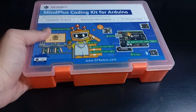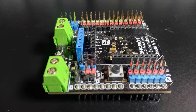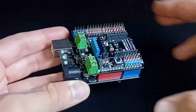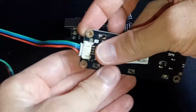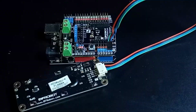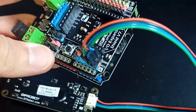Alright, let's move on and assemble our first project. Open your kit and grab the following components: Arduino Uno, input-output expansion shield, LCD module, 4-pin cable. Start by attaching the input-output expansion shield to the Arduino board. Next, connect the LCD module to the shield. Connect SCL to A5 and SDA to A4. Also note that this display works with voltages from 3.3 to 5 volts, so it's safe to use with most Arduino boards.